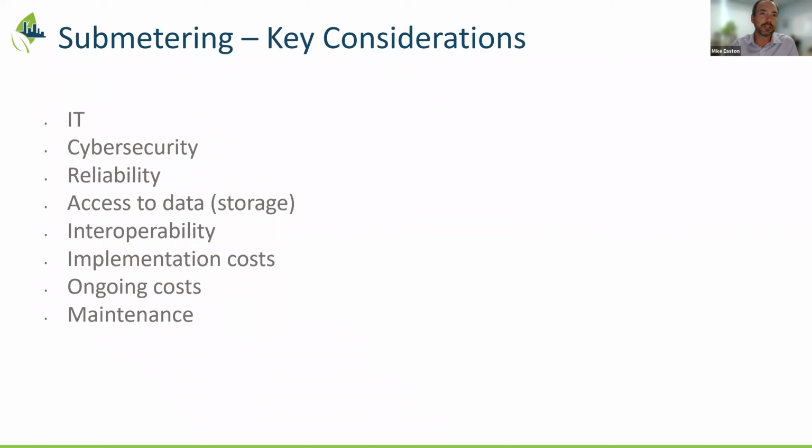One other consideration that needs to be factored in is ensuring that all stakeholders are communicating what parameters or measurements they want out of the meters. If you're installing a meter that's only going to give kilowatt hour consumption or natural gas consumption, but one of the other stakeholders wants instantaneous data, or wants pressures, kilowatt demand, power factor or harmonics, that needs to be communicated early on. Often it isn't, and it can result in a costly swap out of the hardware if the specifications are not meeting what the end operator wants. So those are our cautions.